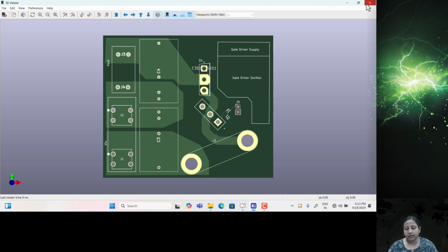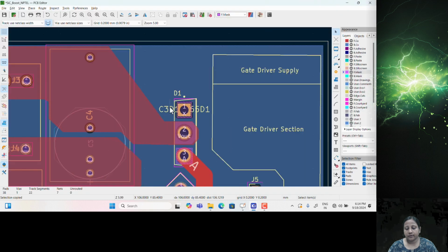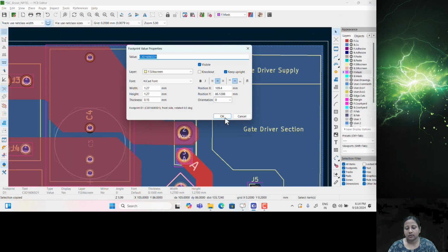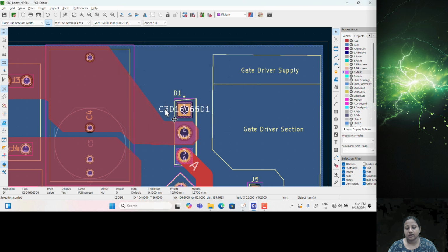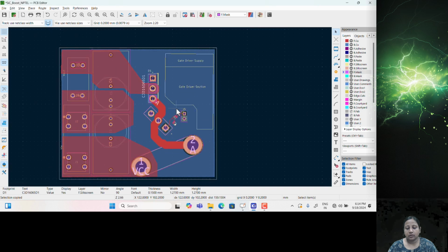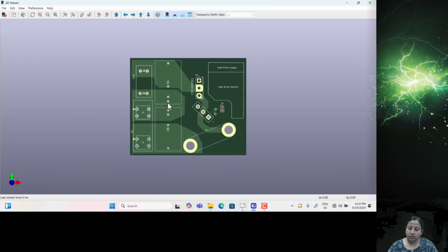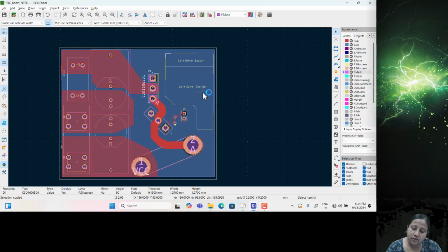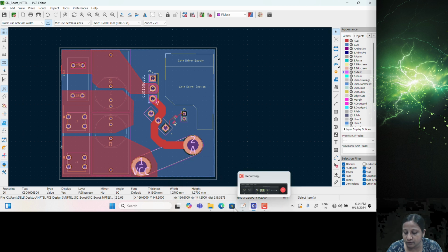This is for the diode, because if it is very thin, then there may be a chance of malfunctioning after soldering due to a connection problem. But if the thickness of the pad connection is more, then it will be much easier to connect the component, and the problem of malfunction can reduce.